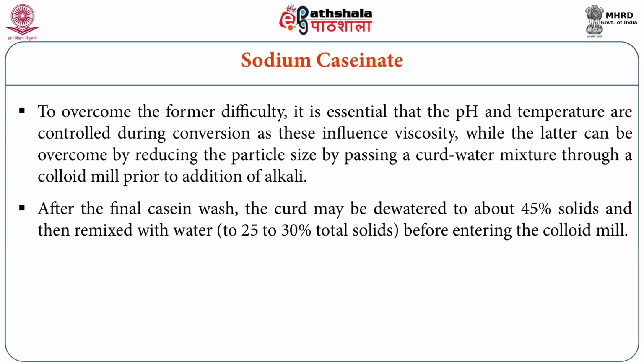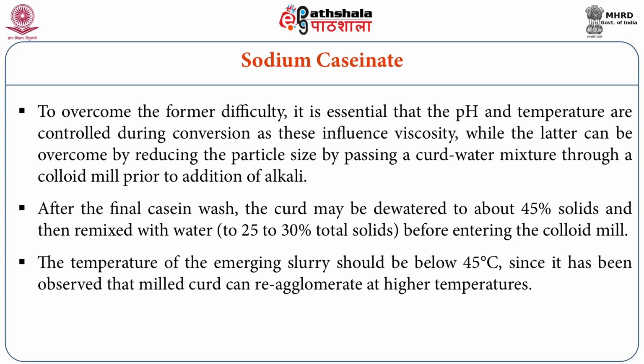After the final casein wash, the curd may be dewatered to about 45% solids and then remixed with water to 25 to 30% total solids before entering the colloidal mill. The temperature of the emerging slurry should be below 45 degrees Celsius, since it has been observed that milled curd can re-agglomerate at higher temperatures. So, temperature has to be below 45 degrees Celsius.